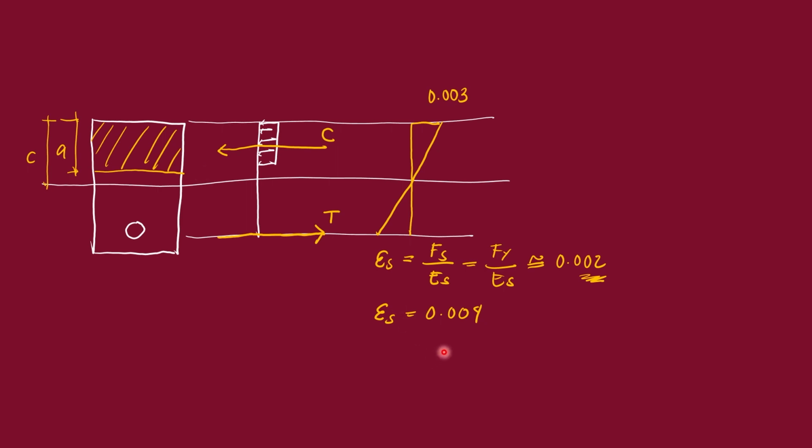So one logical solution so that the concrete does not fail first is, of course, to increase the area of the concrete in compression, just so it will not fail or yield first. So that it does not become compression controlled.